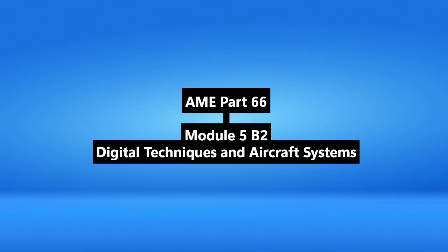Okay, so let's break down the types mentioned. First up, MIL-STD-1553B. What are the key takeaways for that one? Right, 1553B. Key things. It's asynchronous, meaning no single clock timing everything. And it's half duplex: data goes both ways, but only one way at a time. Think walkie-talkie. Okay, push to talk.